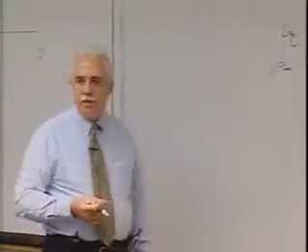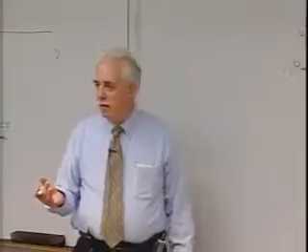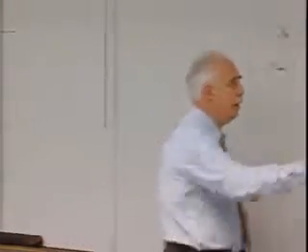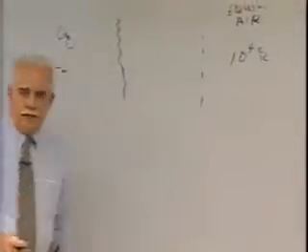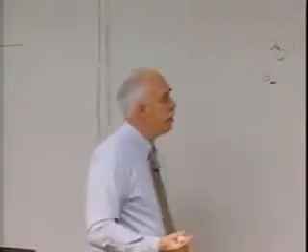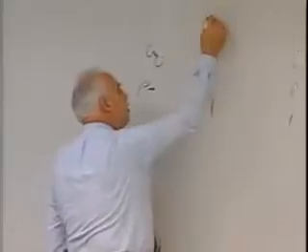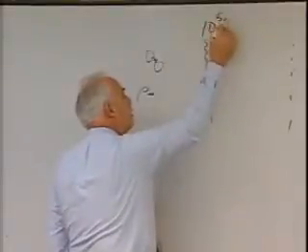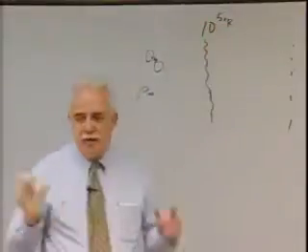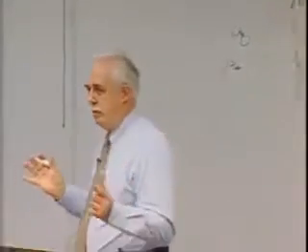Go through a shock, the density ratio is only a factor of 6. Here, the density is 15 to 20 times free stream density. And the temperature goes to 100,000 degrees Rankine if it just stayed as a molecular gas.